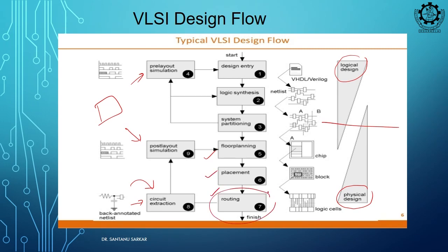Routing is one important aspect in considering low power design, because when we are doing the RTL coding, we generally at the beginning are not aware of the significance of routing. But this may take an appreciable amount of power. A lot of power can be wasted here. For example, suppose you have a block like this, and this block and this block have so many buses.